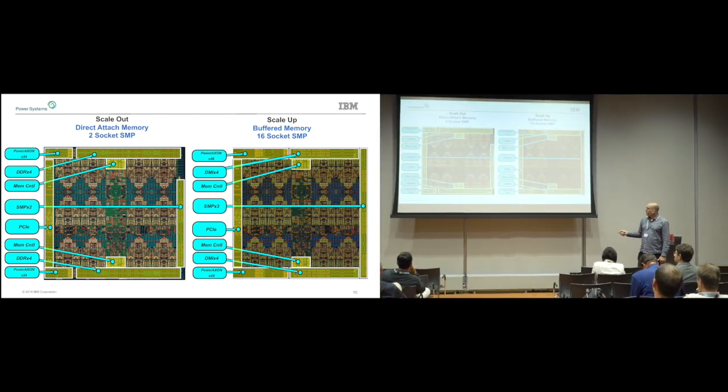This takes up quite a bit of perimeter area, though, right? We've taken up nearly half of our chip perimeter, and this is a very large chip, just to drive 8 channels of DDR. So you can see if we wanted to get to more channels of DDR, it's really not possible, right? We could go to 16 channels of DDR if we had nothing else coming off of our chip other than a little bit of PCIe.